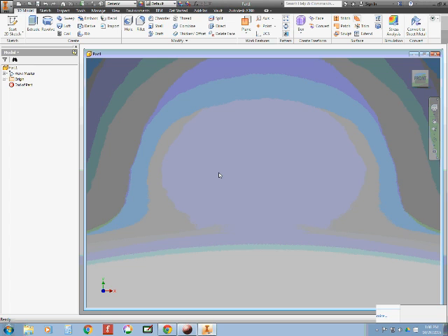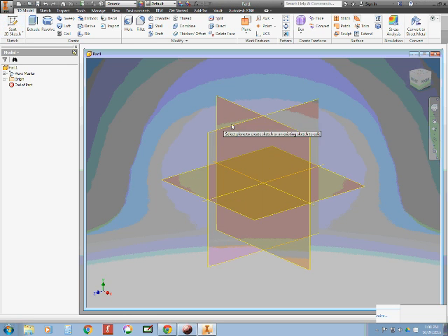Okay, and now let's go ahead and start a 2D sketch. Now I'm not sure how they're set up in the lab. By default, I think the setting is start without a sketch and then allow the user to create a 2D sketch in whatever plane they want. So we're going to start in the XY plane. So you'll click on Start 2D Sketch.